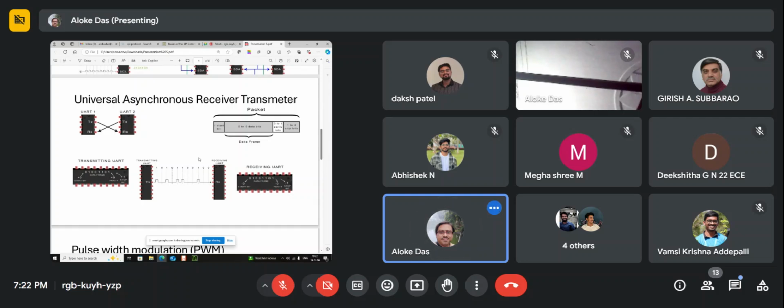But again, you may ask what this bit means, since there is no clock reference, right? This device is sending data, so it definitely has some internal clock. Based on that clock, it is sampling data and shifting the registers, and data is coming out, but that clock is not available here. This one is sitting maybe 100 meters away, and you are not giving the clock from here to there.